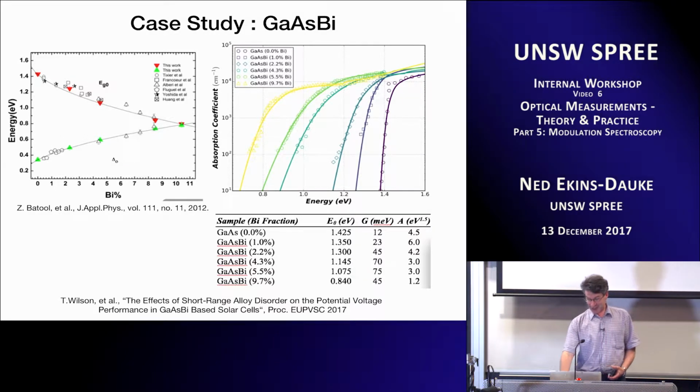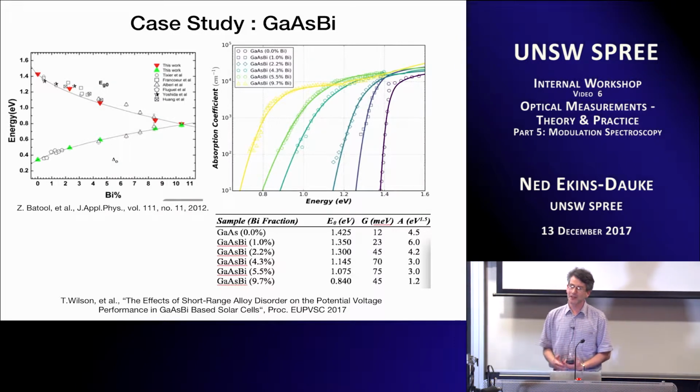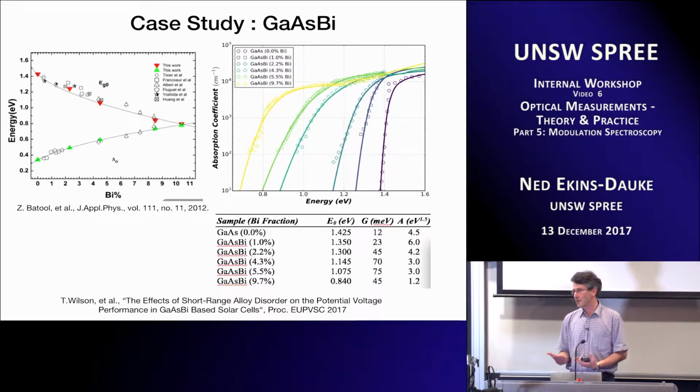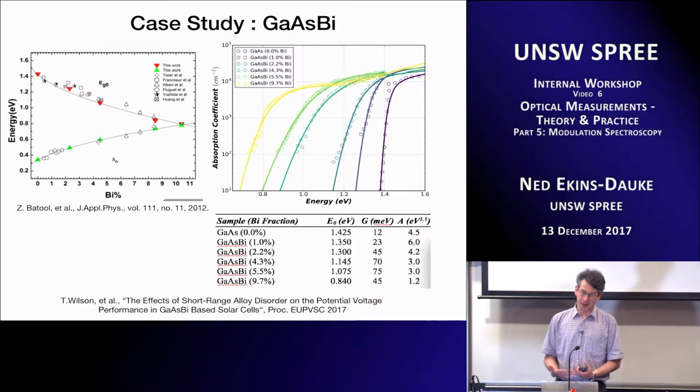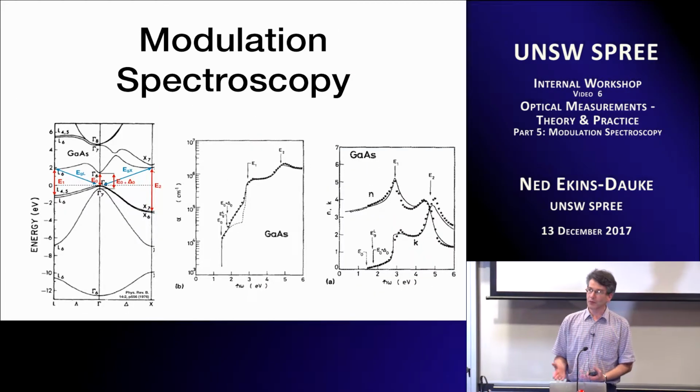That was, I hope folks, you can see now that ellipsometry is hugely powerful, that we can measure N and K. What we measure, as Yvonne said, was psi and delta, but we can then transform that into N and K, and then, as I'm suggesting, we can build physical models around this.